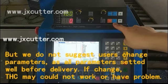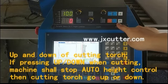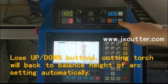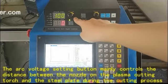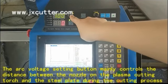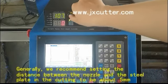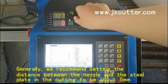Up and down of cutting torch. If pressing up/down when cutting, the machine shall stop auto height control, then the cutting torch goes up or down. Lose the up/down buttons, and the cutting torch will go back to the balance height of arc voltage. The setting button mainly controls the distance between the nozzle on the plasma cutting torch and the steel plate during the cutting process. The number can be adjusted. Generally, we recommend setting the distance between the nozzle and the steel plate in cutting to be about 5 mm.